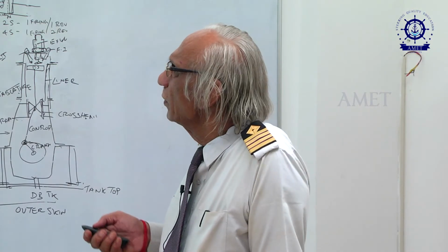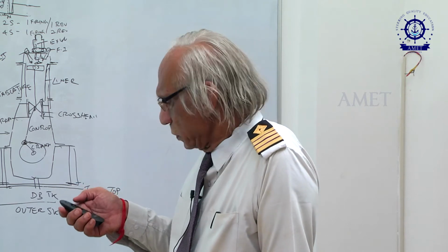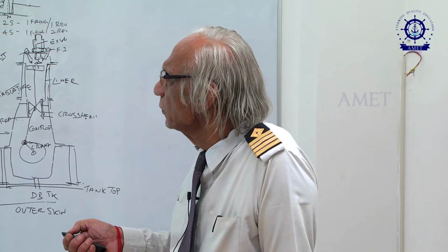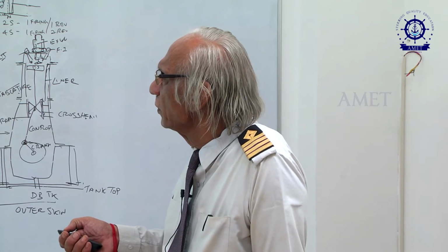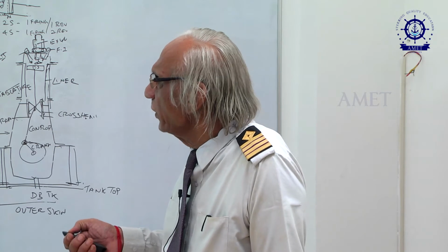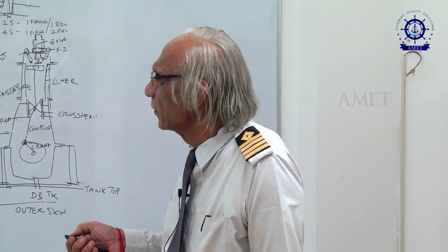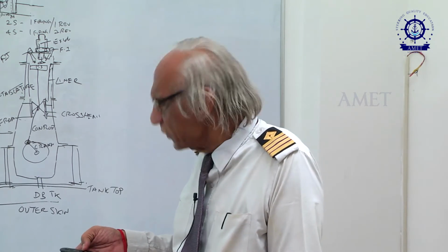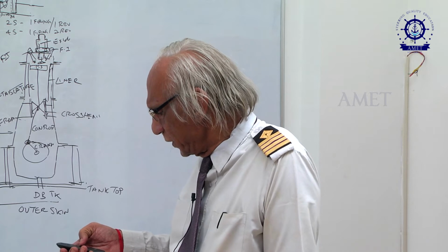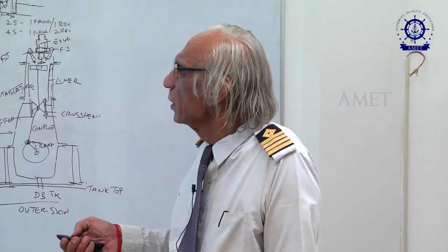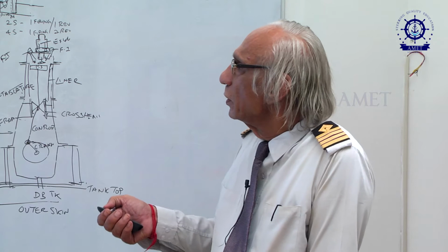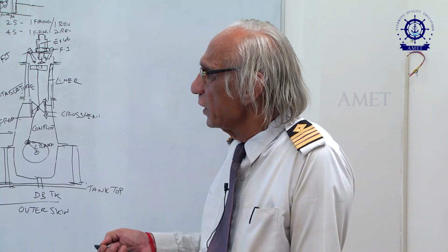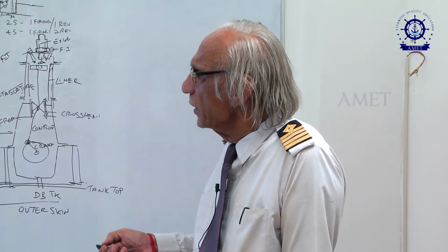As you can see here, the two-stroke engine piston has a very long rod. It is passing through a crosshead and then through the connecting rod. I mean, the piston is not directly connected to the connecting rod. That is the difference. Whereas you see in the next slide, here you see the piston. The piston has a very long skirt and is connected to the connecting rod directly.